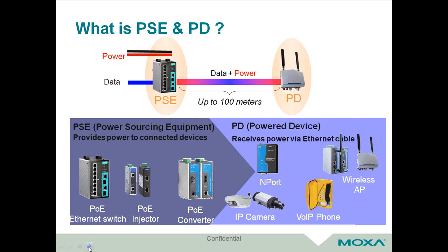Now, Moxa has a very unique offering. We have a media converter that actually provides PoE. So you can go fiber in and PoE copper out. So, there are a lot of choices for providing power. And of course, the PD is just the device that's taking the power. And the PDs are probably the coolest piece of it all. There's access points, there's cameras, there's even device servers now. We make a serial to Ethernet device server that can be powered by PoE, thus eliminating the need for a wall wart and additional power supply. So those are the two main terms there.